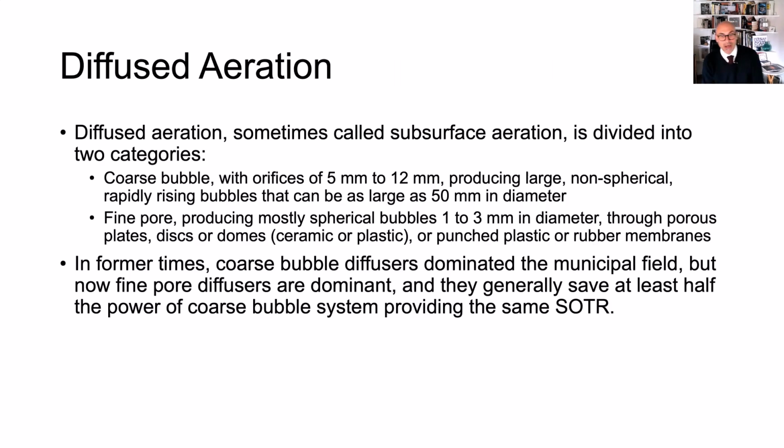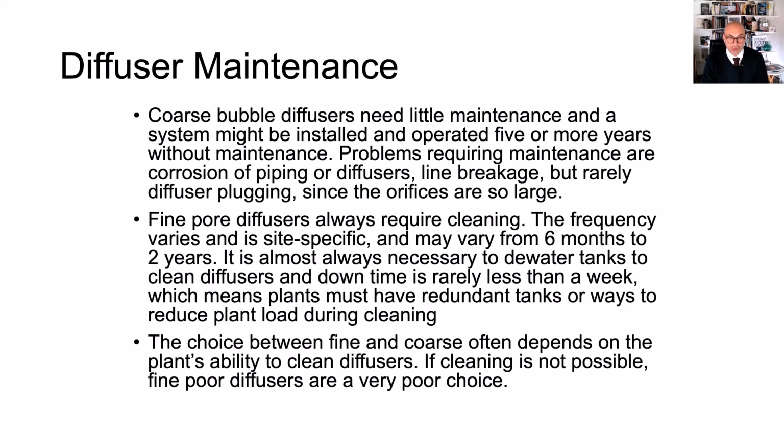Diffused aeration systems are instead the lion's share of the type of aeration systems we have in municipal applications. Coarse bubbles are now confined to mixing channels or degassing channels, where you need to reduce the amount of dissolved gas that you have in a tank. There is a mismatch in terms of depth compared to the clarifier, much deeper than the clarifier. But fine pore diffusers are the most common ones, and coarse bubble diffusers remain dominant in industrial treatment, where you have very high oxygen transfer rate requirements.